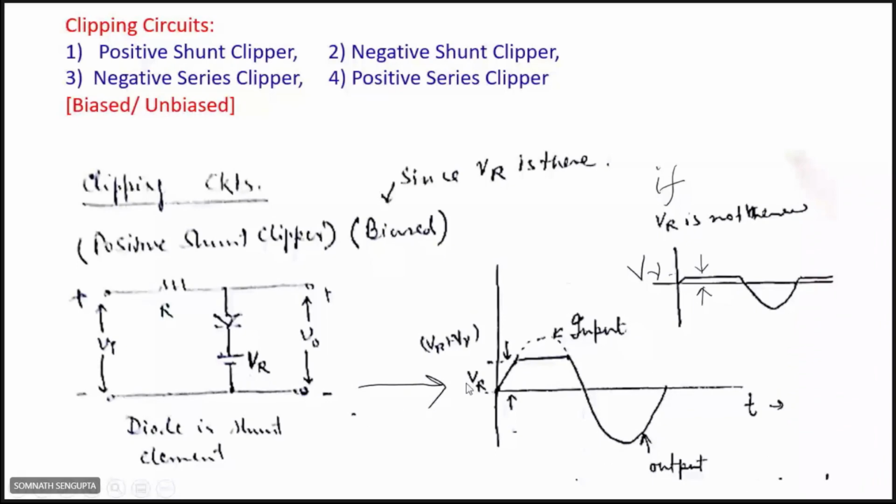The first waveform, you see this waveform, you have to look at what conditions the diode will become on. Can anybody tell for this circuit at what conditions the diode will become on? This has cut-in voltage V gamma. This is the polarity of the cut-in voltage.